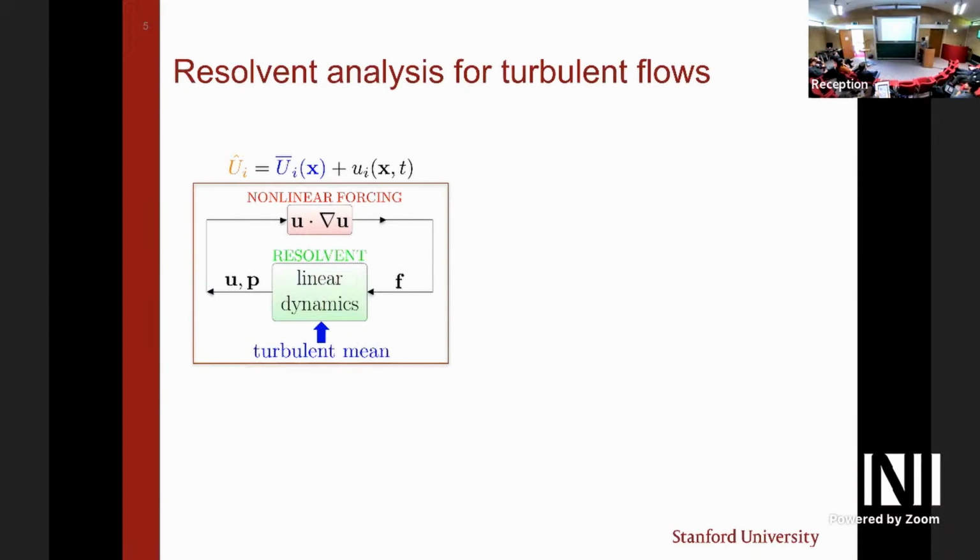And so there's a lot of work being done on the linear dynamics for laminar, transitional, and for turbulent flows. But we want to tackle this whole thing. And so the piece of information here about what makes turbulence tick is this. That's the thing that's going to sustain the otherwise linear dynamics. It's going to move the energy around in wave number space. So for each of these parameter sets, we can write the transfer function relationship between u at that set of wave numbers and frequencies and the input forcing here, and this then is the resolvent.